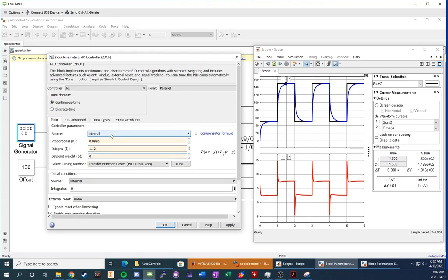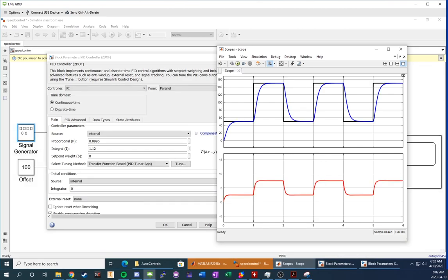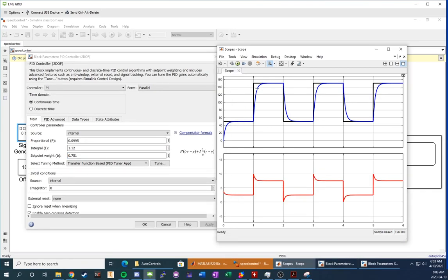We're starting with that set point rate ESP of 0. Now we can take a look at the response and make some notes. Go in there, measure the settling time, how long it takes to get to 2%, and then summarize the results. Next, you're going to do the same thing with the question 11 results, just verifying that those are also correct. In that case, you adjust your set point rate up to 0.751 and check what the settling time is and whether it actually meets the design. Again, take a screenshot and then summarize your responses.